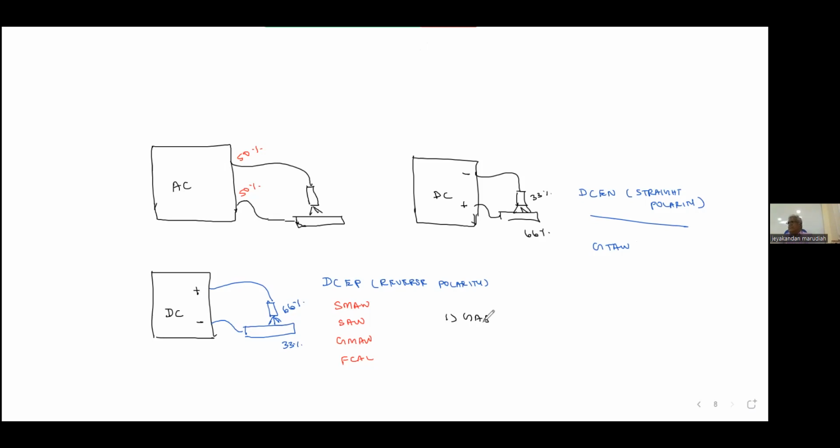The disadvantage of gas shielding is that in windy conditions we cannot weld. It will not give sufficient protection. Another one, we need a very clean surface for gas shielding processes. If the surface has rust, then porosity will come. So gas shielding we are using in GTAW, GMAW, FCAW. FCAW without gas shielding also we can weld.